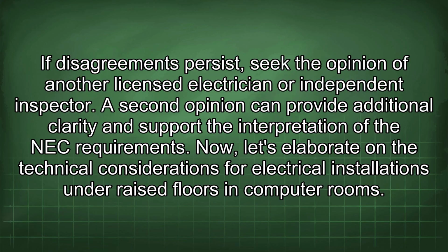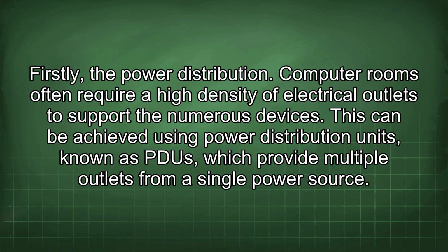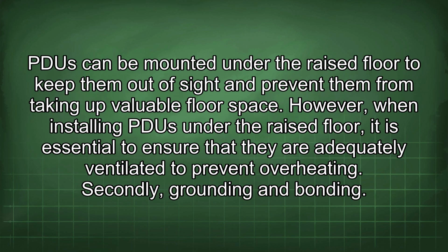Now, let's elaborate on the technical considerations for electrical installations under raised floors in computer rooms. Firstly, the power distribution. Computer rooms often require a high density of electrical outlets to support the numerous devices. This can be achieved using power distribution units, known as PDU, which provide multiple outlets from a single power source. PDU can be mounted under the raised floor to keep them out of sight and prevent them from taking up valuable floor space. However, when installing PDU under the raised floor, it is essential to ensure that they are adequately ventilated to prevent overheating.